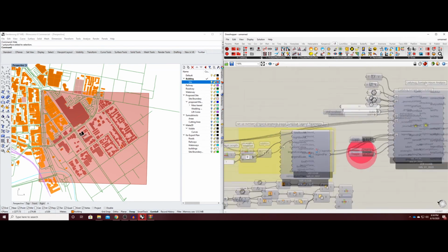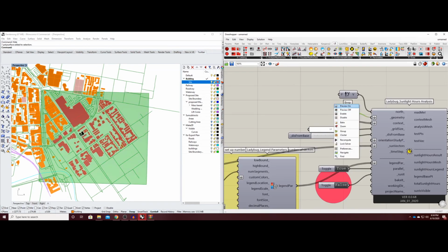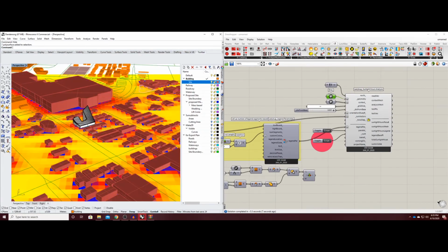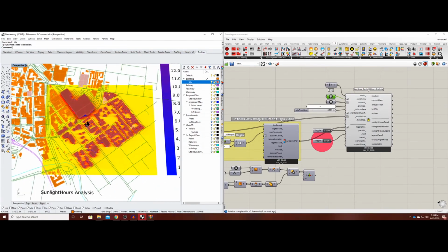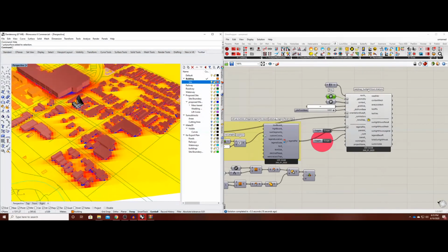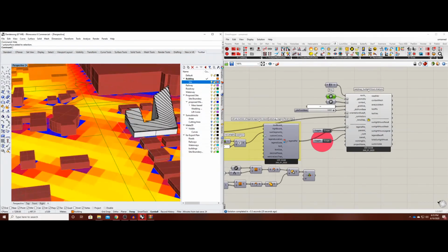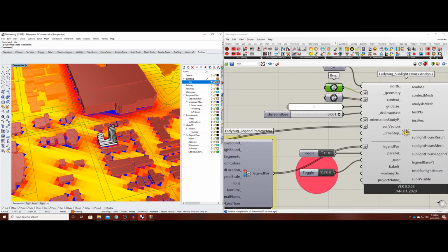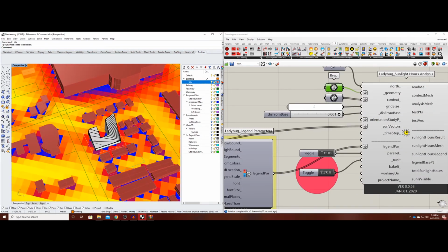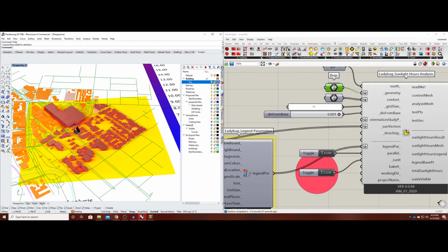So let's start the simulation and see how it looks. After a while, after you've pressed true, it's going to solve by itself. It's going to calculate, and it took me 5.5 seconds. And that's how it looks. You can see that it's quite pixelated because the grid size is 10. If you make it lower, it can be higher resolution, but it's going to take longer.